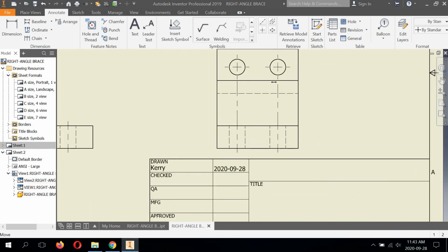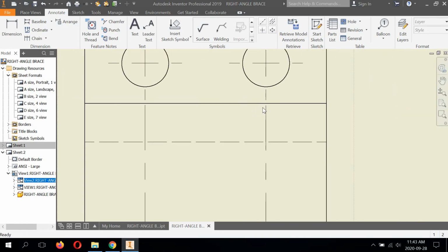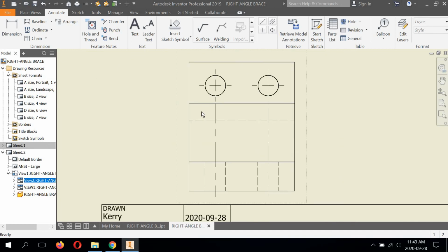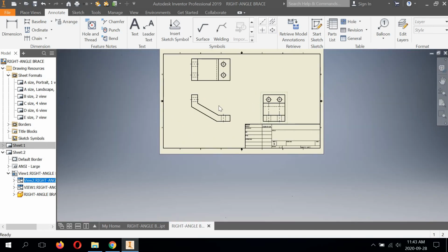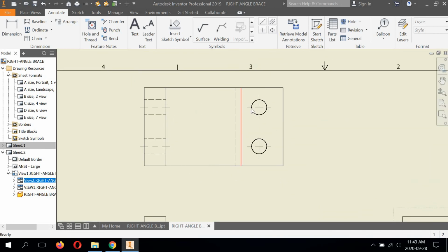So we're gonna do that again. We're just gonna stop. We don't wanna bring it right up to the center mark line. We wanna just eyeball it to stop a little bit before. We wanna maintain that break. So the front view doesn't require it, but the top view does. So don't grab it from the center mark, but grab it from the center line. If you grab it from the center mark, it'll just continue a line solid without that dash every so often.